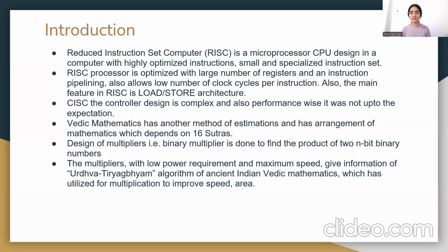The main achievement in this work is that the multiplier unit, the ALU and the accumulator are implemented using Vedic sutras. The main principle used in Vedic mathematics is to reduce the typical calculation of conventional maths to a very simple one, and hence it reduces the overall computational complexity of the whole math. Vedic MAC and ALU are integrated with the other blocks of the processor, and that's how the 16-bit Vedic processor is developed. It reduces the delay by 34% and it saves around 88% power compared to the other conventional processors.